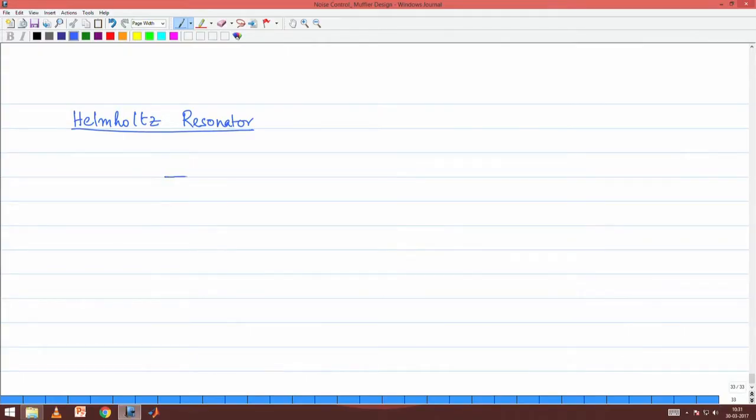Okay. So, this Helmholtz resonator, in one of its incarnations which is easy to understand, is simply two ducts, one with a large cross section and the other with a small cross section. This is a small cross section, this is a large cross section. So, S prime is much smaller than S, and accordingly there are two lengths, L prime and L. We are going to look at frequencies which are small, so KL and KL prime both are small.